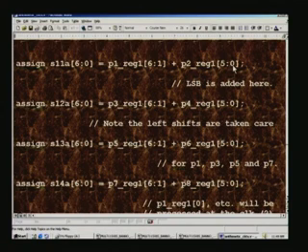Note that we are taking the very LSBs here, 0 through 5, a total of 6 bits, and here also 6 bits, and it is equivalent to having P2 as the second one. If you take this P1 number 6 through 1 here, then the 0 bit you also assume, and this particular 0, after left shifting, should align itself with 1. That is the reason why we are aligning 1 and 0 here, and it is equivalent to left shifting by 1.